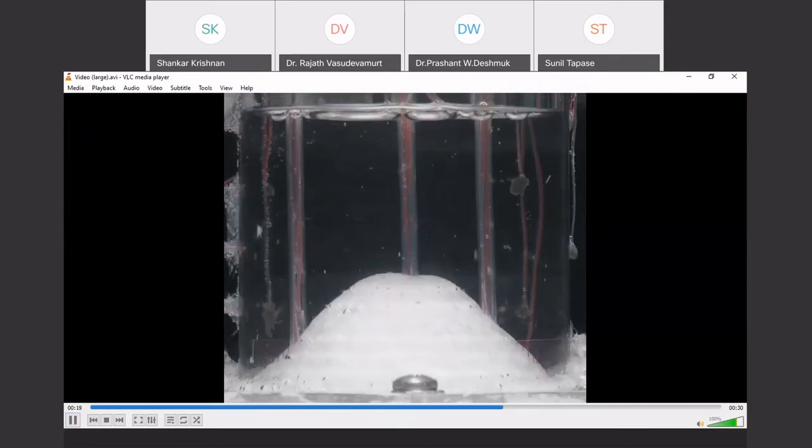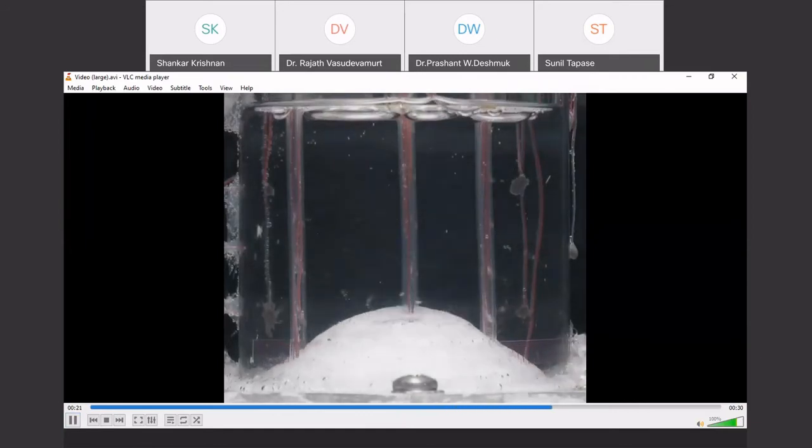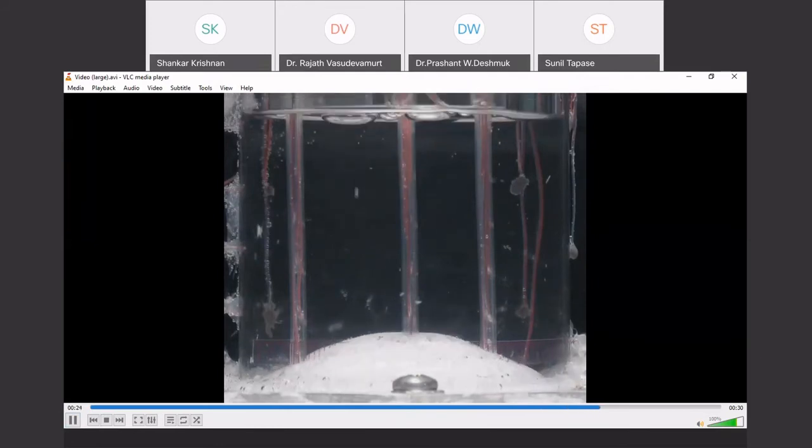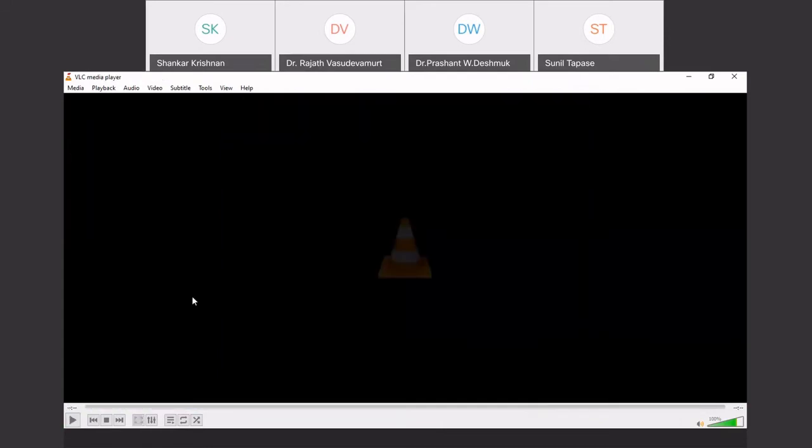Okay, thank you. So here, this is an experiment with solid liquid phase change material. And these phase change materials are good only until they are in the solid state. Once the solid becomes liquid, then they don't offer the latent heat. So they are meant for applications where there are transient pulses.